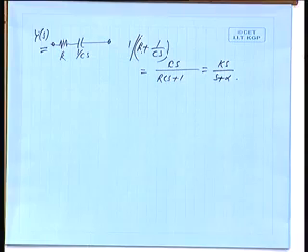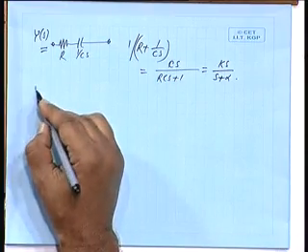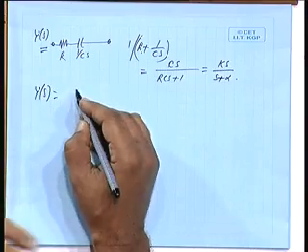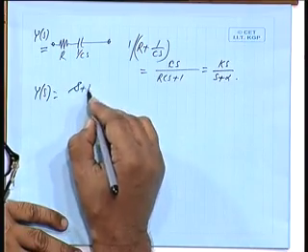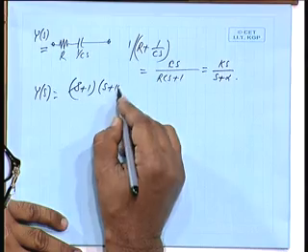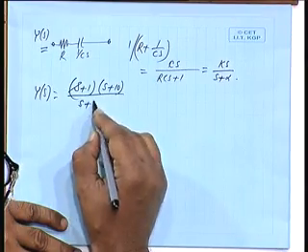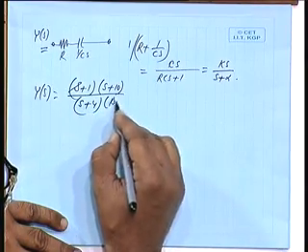So, mind you, Foster 1 starts with impedance, Foster 2 starts with admittance, Cauer 1 starts with a ladder structure with a descending order of S, S to the power 4, S to the power 3 and so on. In case of Cauer 2, it is in the reverse mode. So, let us see this particular example Y(S) equals (S plus 1)(S plus 10) by (S plus 4)(S plus 16).